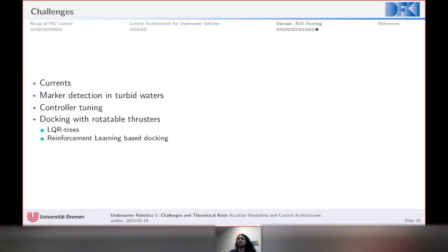One of the things that we're trying to do, because also of the scenario that we had with space exploration, or if you try to do, for example, very long descents, it's quite counterproductive to just propel yourself with a thruster all the way down. So there is a variable buoyancy engine inside of it, which is basically just two balloons or two bladders filled with oil. And if you pump this oil inside of the vehicle, then you are heavier.